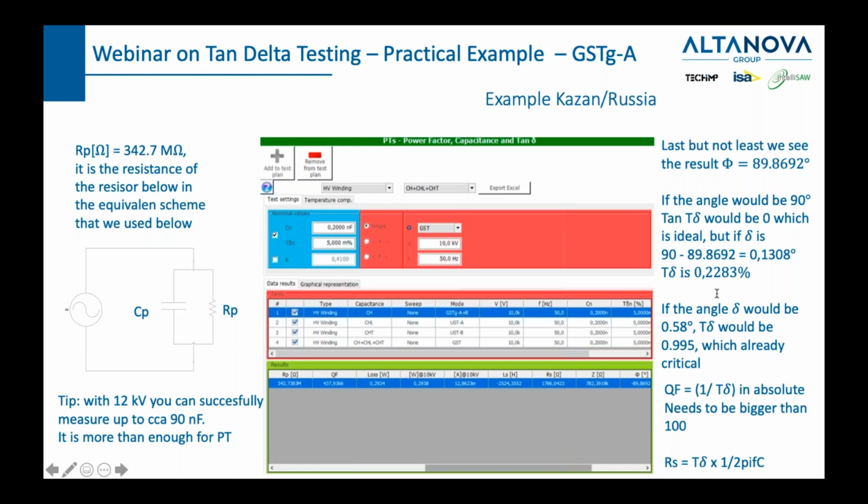If you have the chance to separate each phase from one another, so phase A separate from phase B, separate from phase C, then you can test each phase versus ground. By the way, when you're doing the motor or generator testing, then you are testing the stator winding versus ground. So that's the first step. Can you open the star and can you test each phase versus ground? If not, then you test all three phases connected together versus the ground.